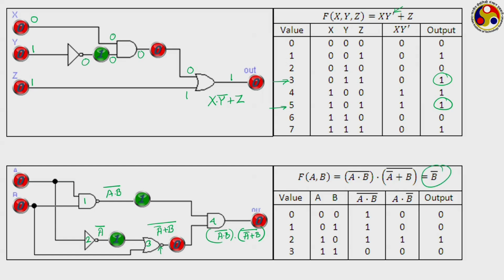We can see in terms of a few examples. Let us say one example is already worked out here. Instead of that, let us take A is 1, B is 0. Then what will be the output from the NAND operation? A 1, B 0, had it been an AND gate, your output would be 0, but it is a NAND, so your output will be 1. Now, after the NOT operation, A leads to 0, and because that is A bar, now this 0 and 0 from B, they both go to NOR, and as both are 0, had it been an OR operation, we would have got 0, but it is a NOR, so we are getting a 1.